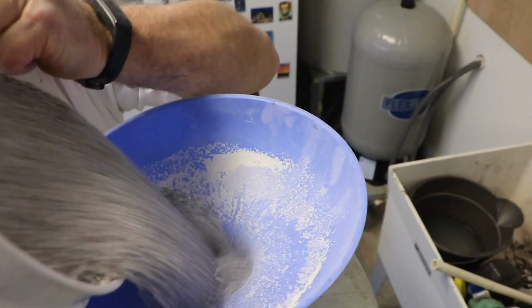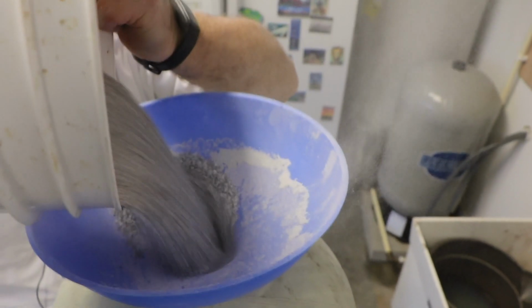Point of entry whole house calcite filters require at least an annual maintenance. And what happens is the calcite actually dissolves. And it dissolves because of that universal solvent thing, and the water is actually dissolving the mineral, and it's picking it up, and that's what buffers and raises pH. So eventually the calcite in that tank is going to go away. Typically on an annual basis, you're going to add more calcite back into that tank. Depending upon your flow rates and the size of the tank that you have is going to determine how much calcite you're going to need to add back in.